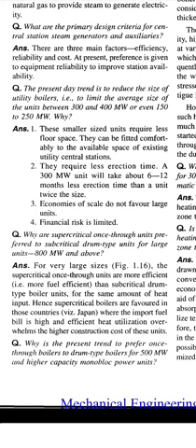Next question. Why are supercritical once-through units preferred to subcritical drum type units for large units of 800 megawatt and above? Answer. For very large sizes, the supercritical once-through units are more efficient than subcritical drum type boiler units, meaning more fuel efficient for the same amount of heat input.